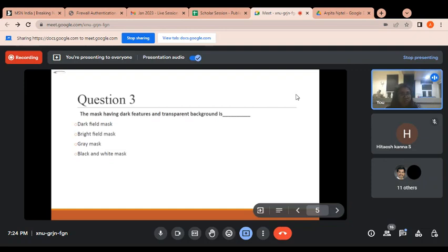Then we UV expose, do the lithography process, and dissolve in a solution. The desired pattern depends on the characteristic of the mask, whether it is dark field or bright field, and on the type of photoresist, positive or negative. Then the pattern is transferred from the mask to the photoresist, and then, after some processes, from the photoresist to the desired device like SiO2. Now you can understand the difference between the mask and the photoresist.